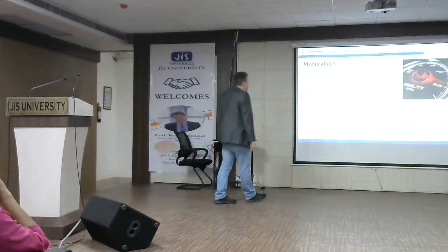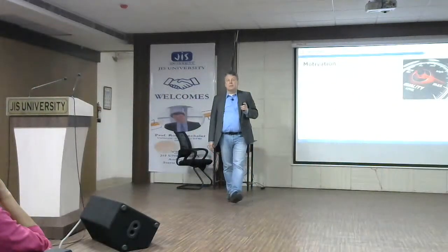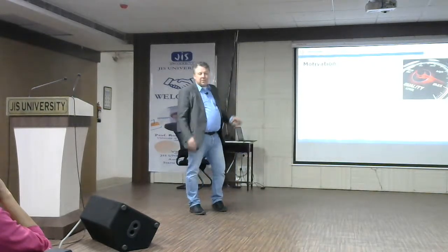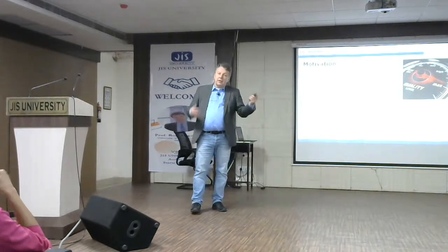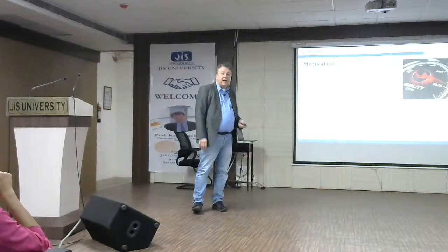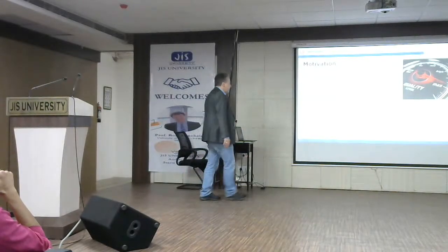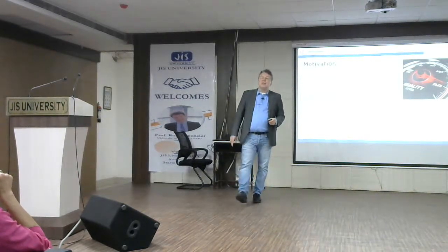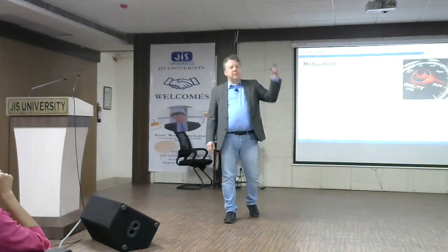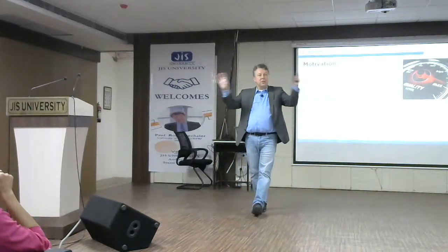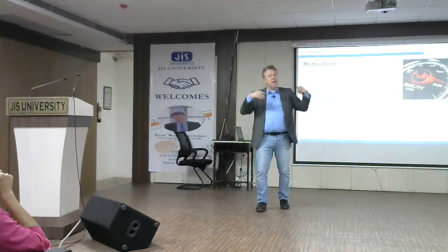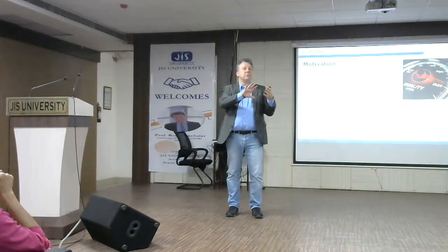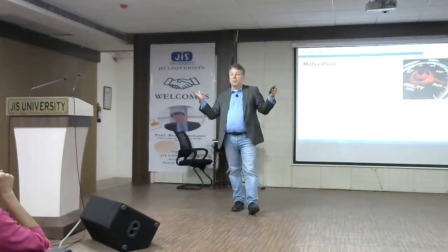So the major motivation is that we want to really ensure 100% correctness. Everything that is below 100 is not satisfying, it's not okay. And that is exactly what companies like Intel, AMD, and in Germany also Bosch, Siemens, with whom we are collaborating, are applying. There are two main tasks. One is equivalence checking, and one is so-called symbolic reachability analysis. Equivalence checking means that you have a specification given and an implementation, and you want to know whether this matches. Someone says, build an adder circuit, and you do a design, and now you check, is this an adder, yes or no? This is the equivalence checking problem.